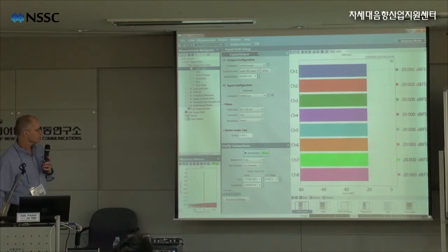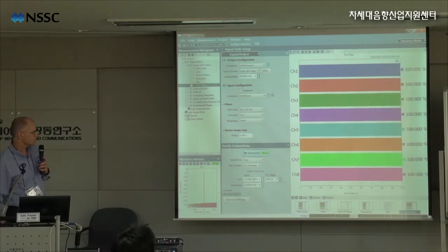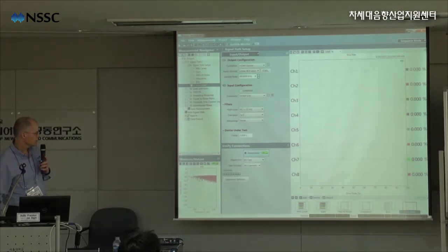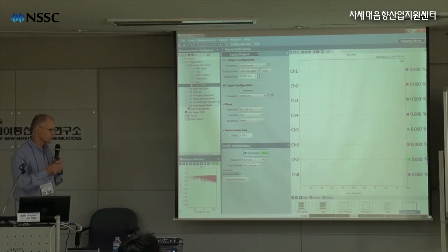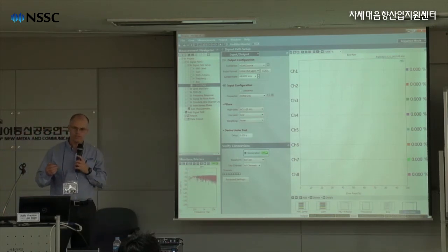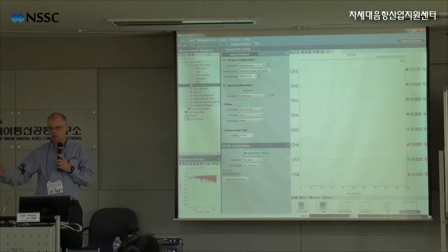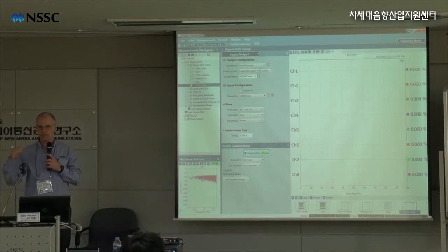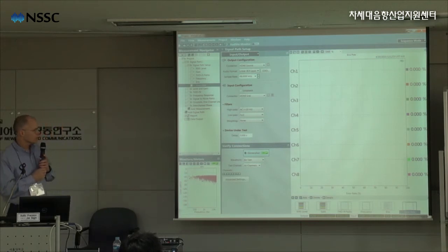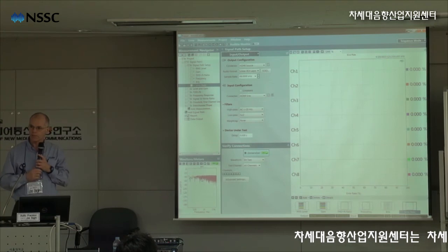Now we have a test for bit exactness, and it's shown over here as error rate. It doesn't work with the sine wave, but we have a special signal inside of the APX analyzer called bit test. If you look at the bit test signal, it's a pseudo-random noise signal, but it's a pattern, a sequence of bits. The generator generates a certain sequence, and the analyzer knows each bit that's coming in. So it's able to compare the input stream to the output stream on a bit-by-bit basis.